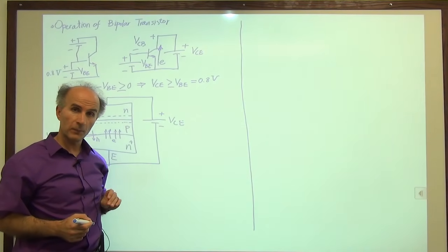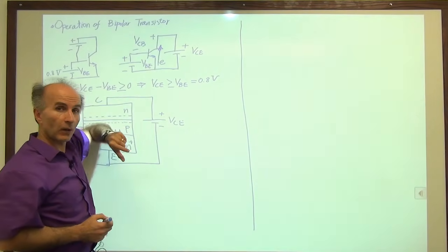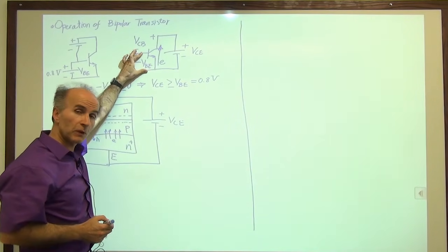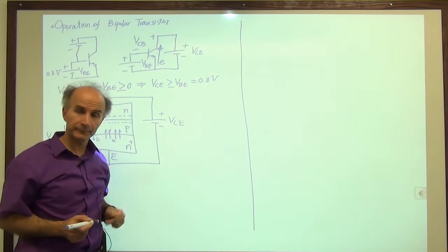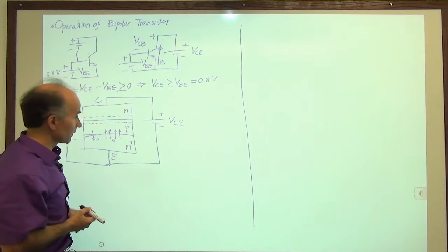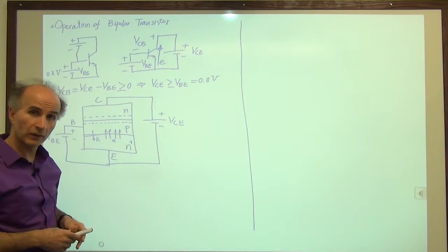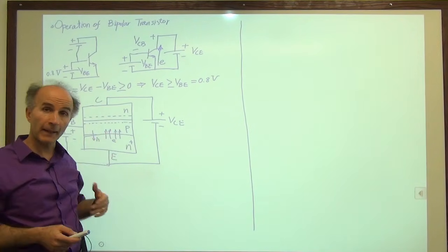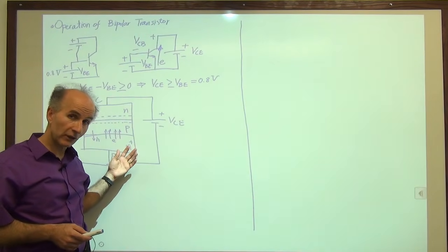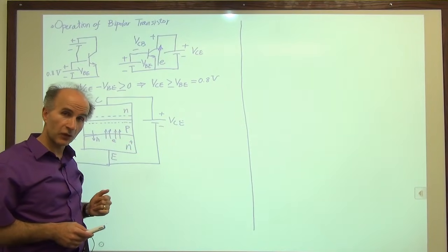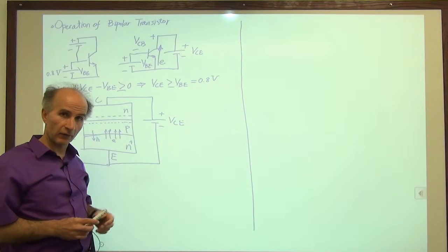So that's very interesting, because we managed to create a current between the collector and the emitter by applying a forward bias between base and emitter and a reverse bias between collector and base, or zero bias. All right, so that's what we have so far. Now, we still have to take some steps to get to the point where we understand why this might become an amplifying device, why this might become a voltage-dependent current source, as we envisioned at the beginning of this lecture. But that's okay, we'll go slowly and understand everything.